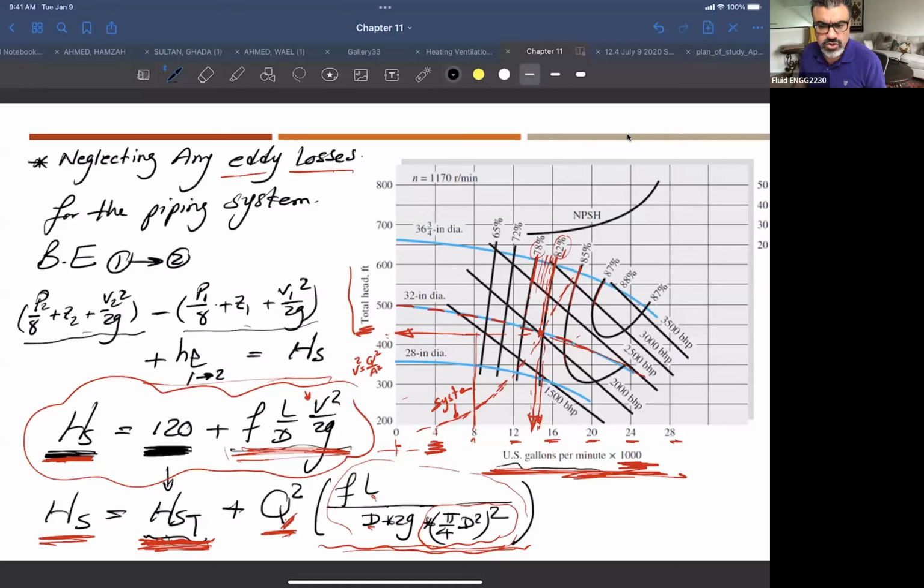But the centrifugal pump is very commonly used for many applications. We also said we have a limitation on these pressures. The pressure at the exit can be controlled by a valve, and you don't have to have flow coming out of the pump all the time, even if you close the valve completely at the exit. It doesn't mean that you are going to do this. It means that this type of pump operation is different from the positive displacement pump, and in this case, you are not expecting this pump to operate at very high pressures.